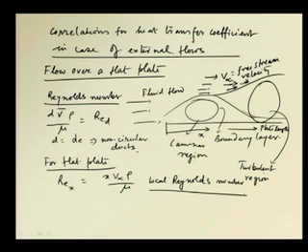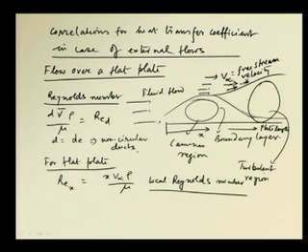And what happens in case of flow over a flat plate is that, because this is the local Reynolds number, in the initial stages, that means up to a certain length of the plate from the leading edge, the flow is laminar, as we can see from the figure. In this region flow is laminar, and then there is a transition that takes place here. This is the transition zone and this is the turbulent region. So, by change of x from the leading edge, the value of the Reynolds number will change, and that will finally dictate whether the flow is laminar or turbulent.